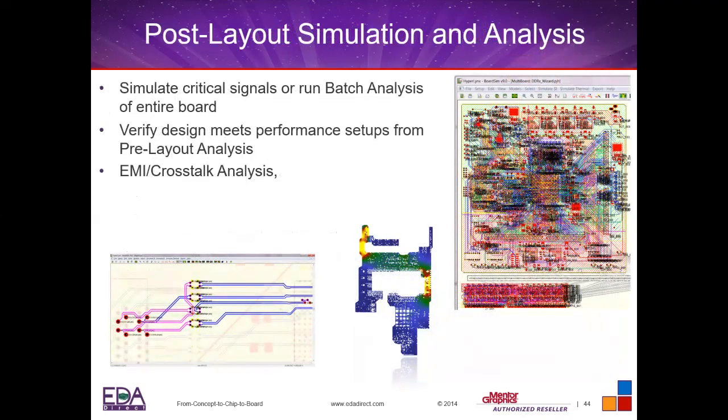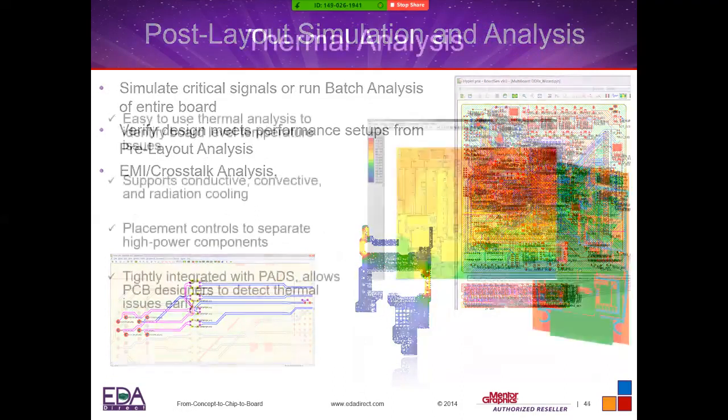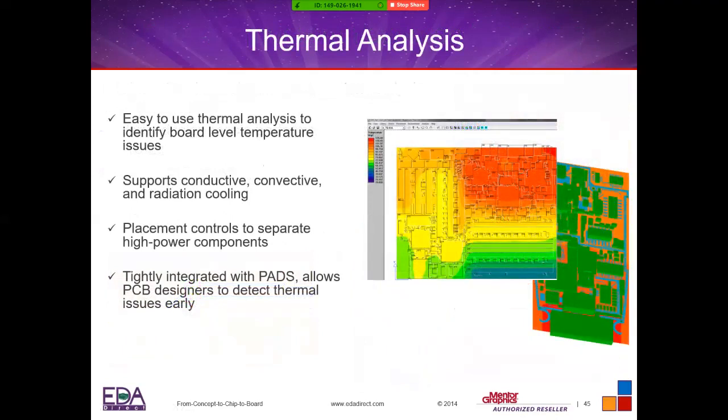You also have post layout simulation and analysis. So for those of you that send a design out and want to check maybe a clock line or something that's sensitive in your designs, you have full capability to do that in the post layout. You will also have thermal analysis capabilities. So you will be able to check out where you're having some temperature problems, should you need to add heat sinks or mounting holes. So full thermal analysis tool there that you can use.